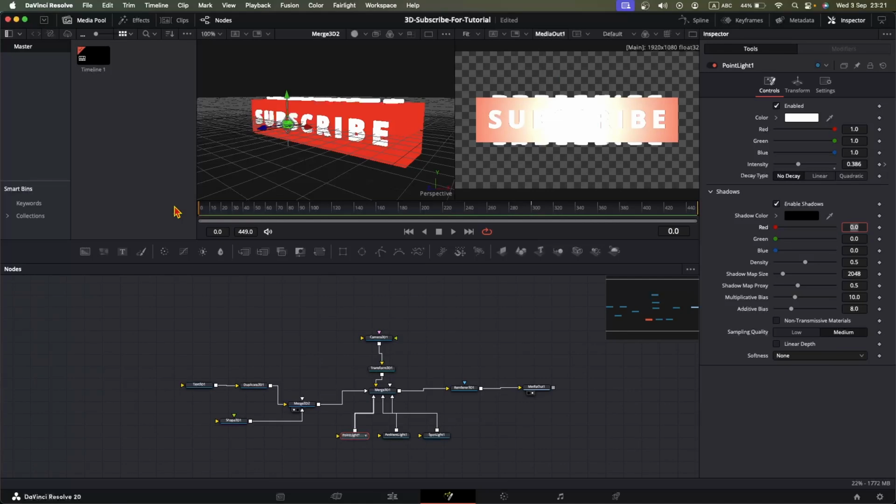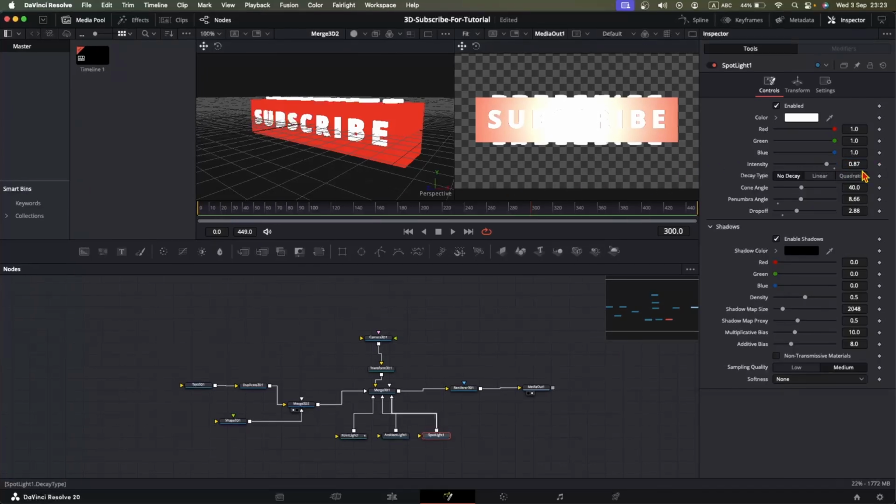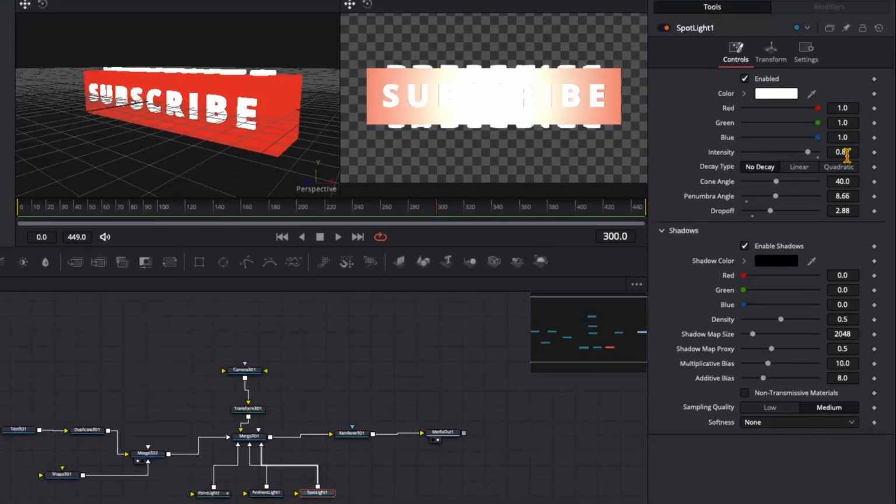And go to frame 0 again. Change the intensity to 0.543. And this automatically adds another keyframe in the frame 0. Go to the spotlight and change the intensity to 0.629.